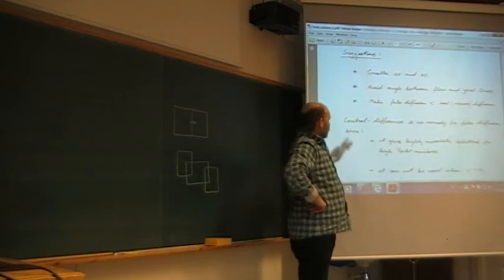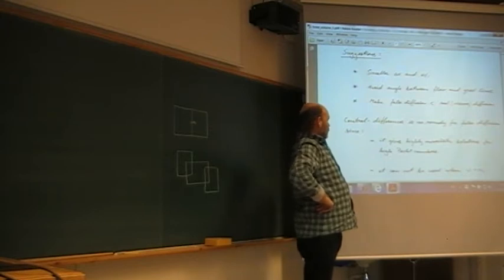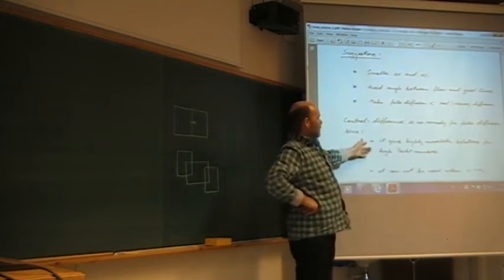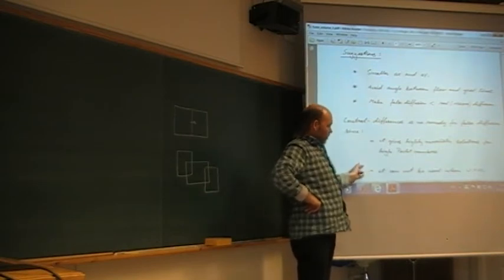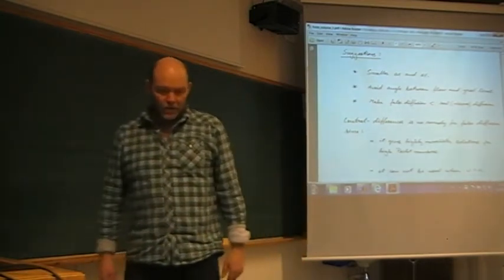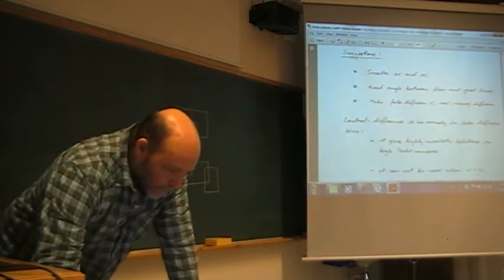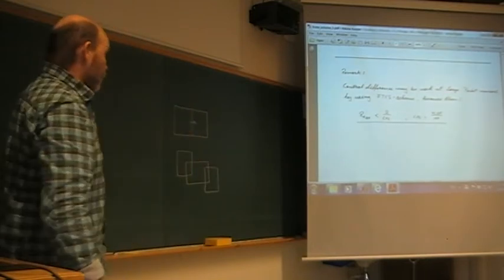And Patankar says that central differences can't be used. No remedy for false diffusion, gives very unrealistic solutions for high cell Reynolds numbers, that's correct. It can't be used at all when you have zero viscosity, also true. But I don't think that's the entire truth.